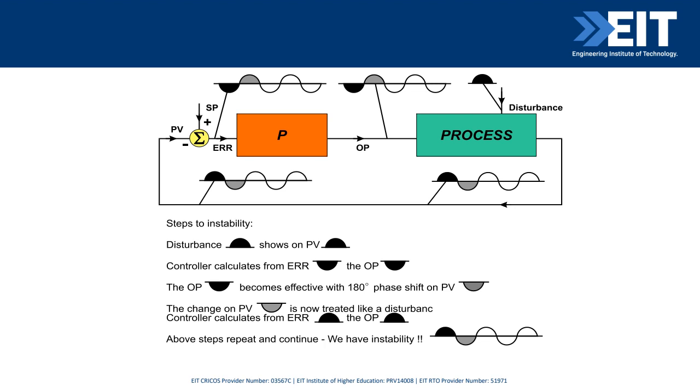Because you're going to actually upset the calculation. As soon as you have I and D in there when you're trying to work out your tuning constants, you will upset the calculation because you're adding a phase shift, a phase lag, into it. You're trying to find out what the actual process phase lead or phase lag is.